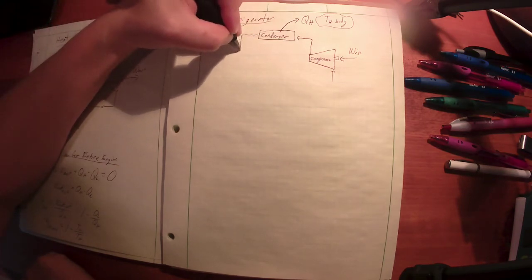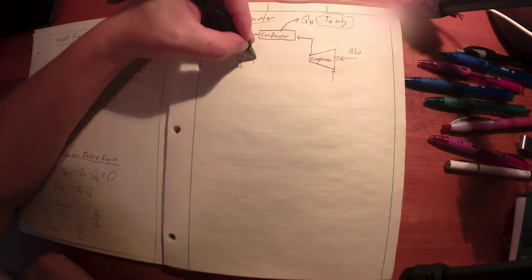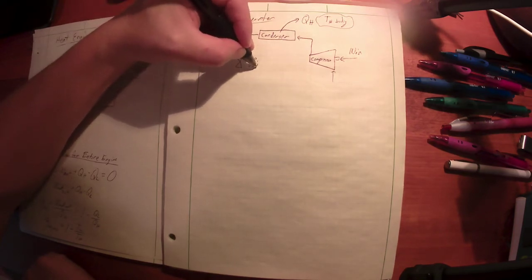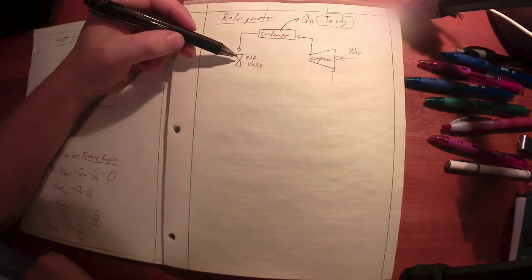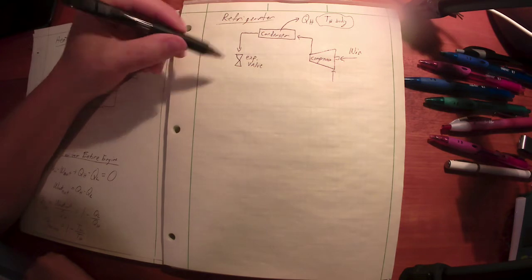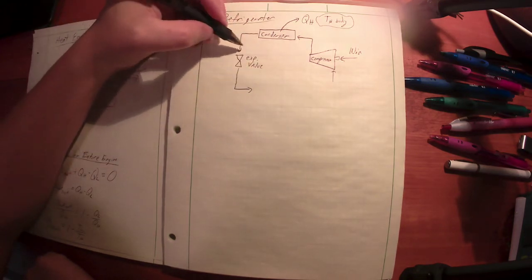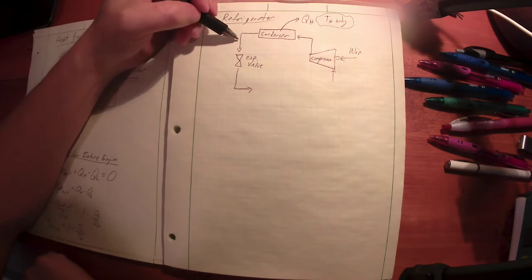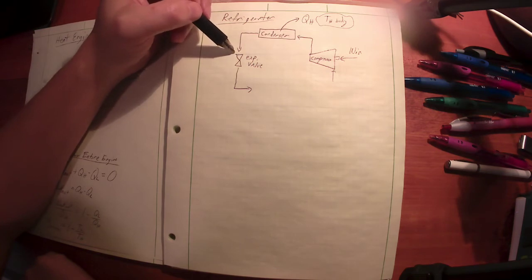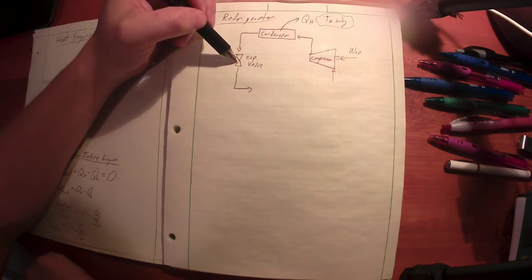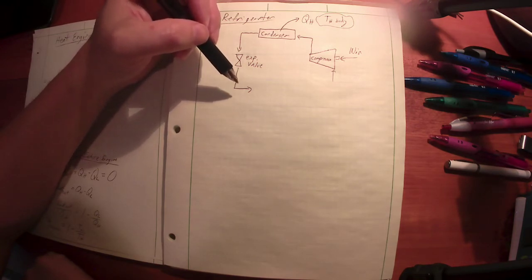From the condenser, we run into what we call an expansion valve. Now, if we had a lot of time, or if we were setting you up for a Thermodynamics 2 course, we'd really talk about supersonic flow, compressible flow, and what happens through a throttling process. For us, we're just going to say, if I take a high pressure fluid, because it's coming out of the compressor at high pressure, and I allow it to expand, it's going to go to a lower pressure and a lower temperature.